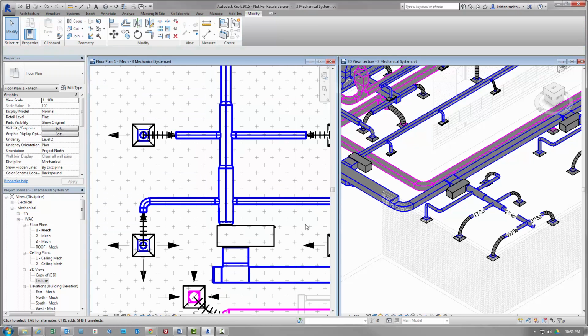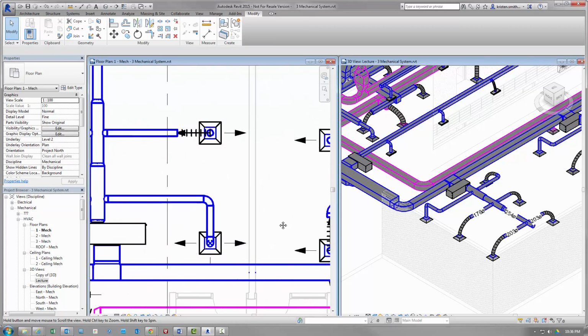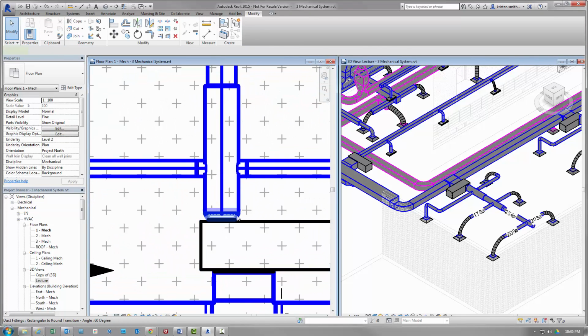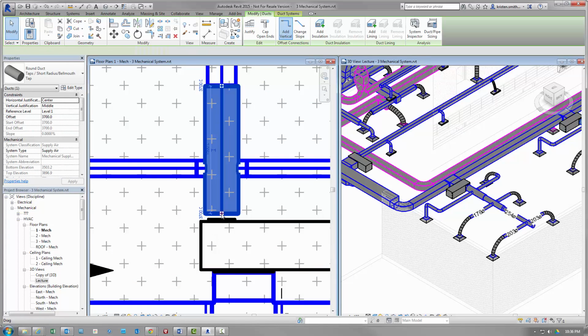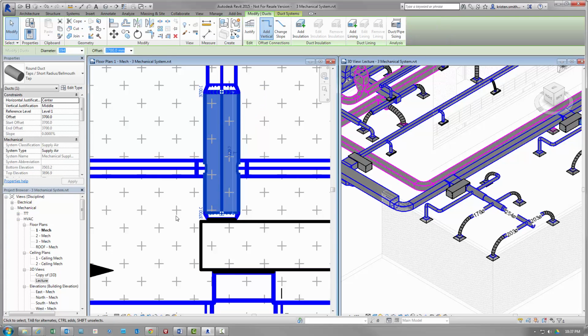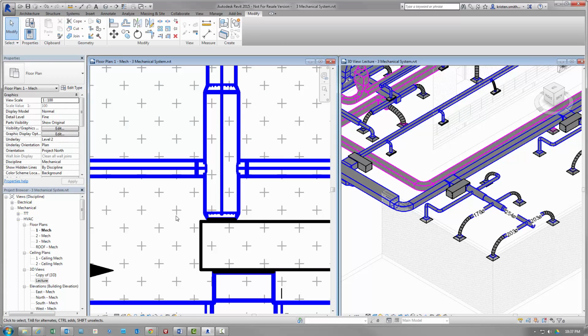Although we did not show it in the demonstration, piping works similar to the duct. I can place the pipe using placeholder tools and then convert to actual piping with connectors using the Convert Placeholder geometry. It is important to be able to draw these schematic one-line representations and not be confined to actual geometry until sizing. You can utilize the interference detection using the placeholders to find collisions, even though the geometry is not shown.